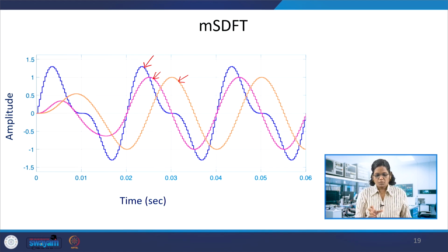The modulated SDFT uses the modulation property of the SDFT, pushing all the bins being required to the kth bin and computing the SDFT. So we have seen the DFT case, and how to use the shifting property of the DFT, that is, if the signal is time shifted, what should be its DFT. Using that, advancing one sample every time, we saw how to use the previous instant DFT to compute the current instant DFT through the sliding DFT. And the SDFT variants are used to reduce the computational complexity, and to reduce the instability problem in the SDFT.